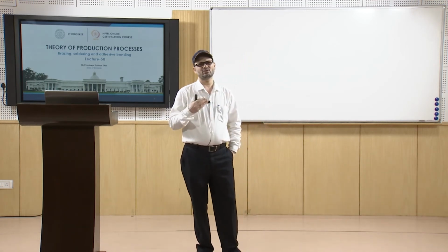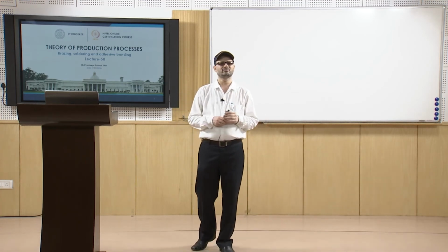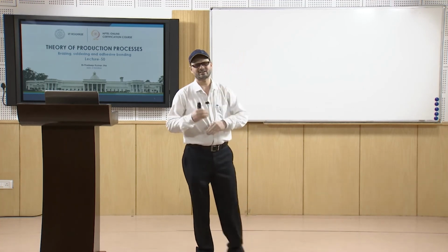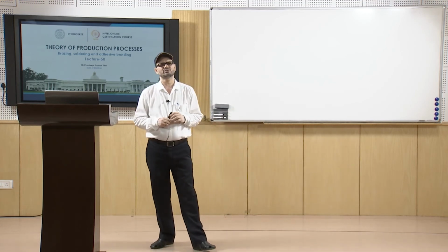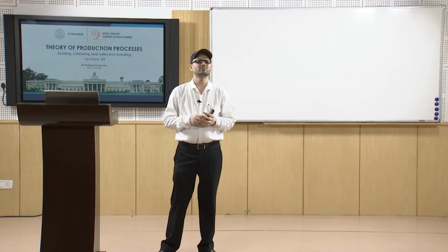Now in adhesive bonding, two kinds of attraction forces are developed. One is the polar forces, because of dipole creation between the adhesive and the relatively brittle oxide film. Another is the van der Waals forces, which are generated between the adhesive and the clean metal. That is the concept of the strength which develops in adhesive bonding.